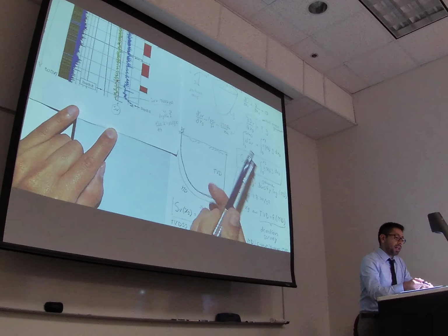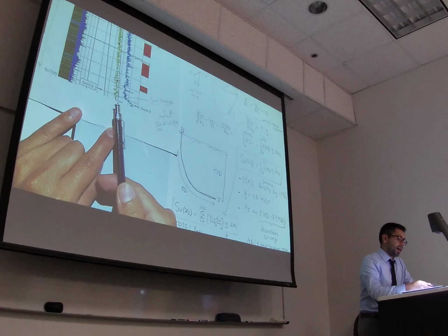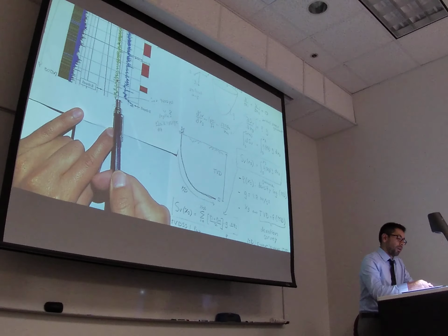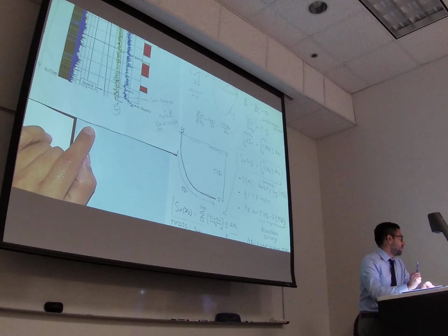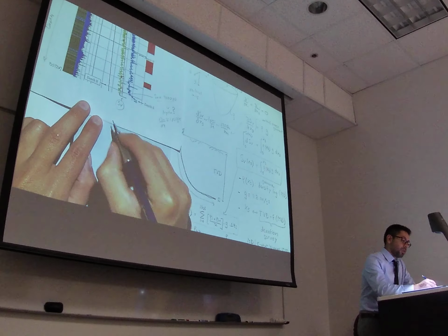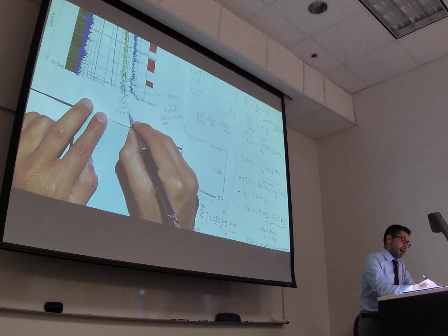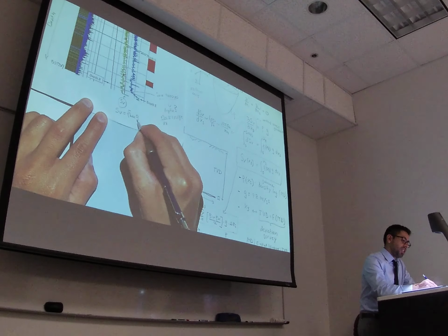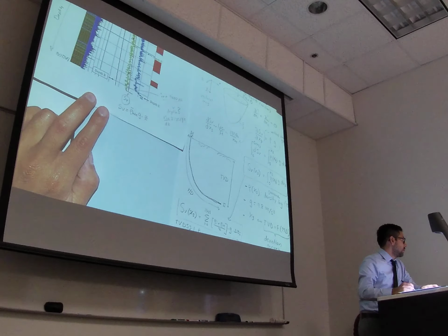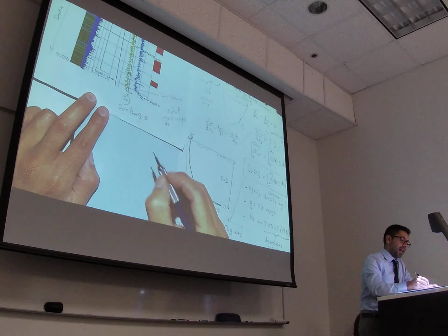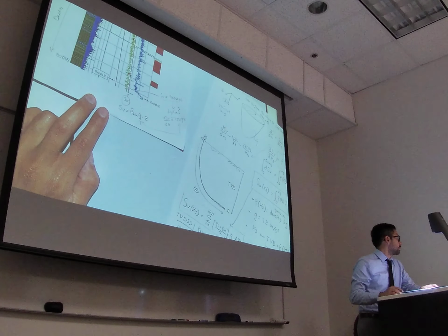So if we know the gradient and we know what is the maximum value or the value of vertical stress, we can tell what is the depth, right? In this case, what we use is just SV is the average bulk density times G times depth, in which this value is 1 PSI per foot.